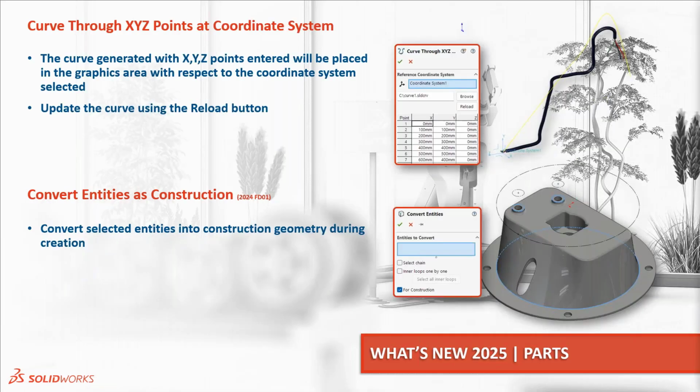We also have an announcement at the curve level. Now the curve through XYZ points can be created with reference to a coordinate system. The curve generated with the XYZ points entered will be placed in the graphics area with respect to the selected coordinate system, as you can see in the screenshot on the right-hand side of the presentation. We can also convert entities as construction. While using Convert Entities, which is available in sketch mode, we can convert the entities into construction geometry, as you can see in the screenshot.